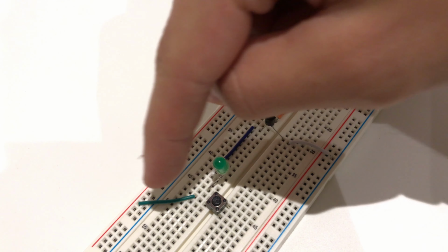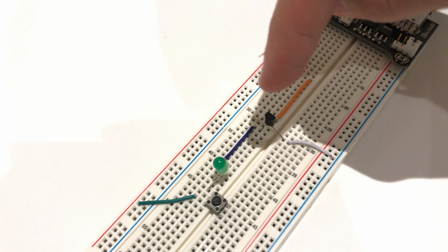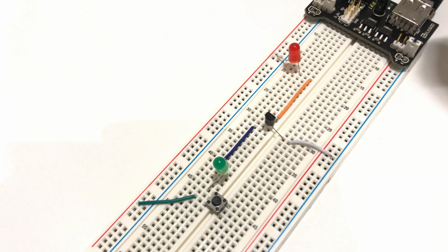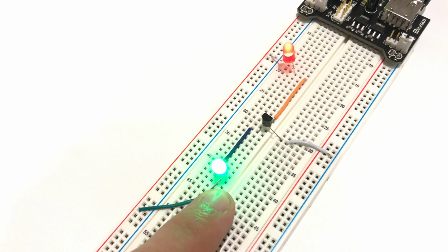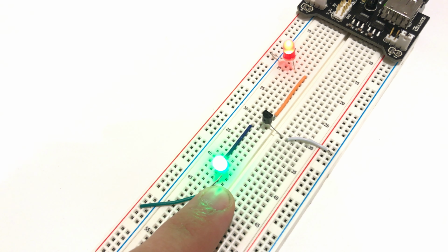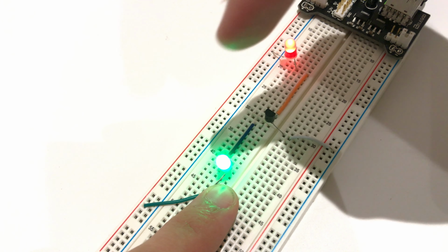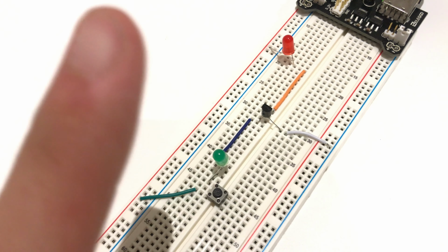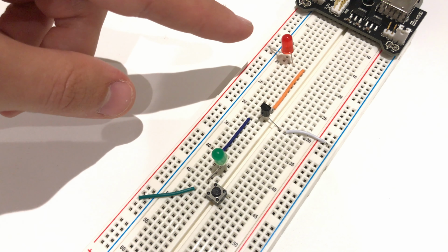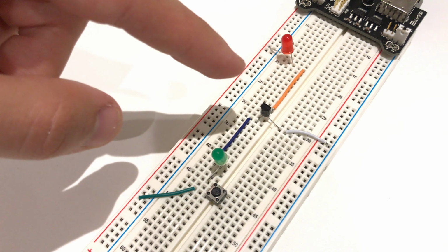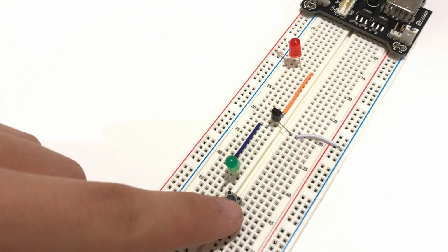So when this button is pressed, power can run through the button, through the LED, into the base, out of the emitter to ground. Allowing current to pass through the base, as shown by the green light, we can see that current is also able to pass through the collector to the emitter, as shown by the red LED. And when no current passes into the base wire of the transistor, we can see that no current can pass through the transistor from the collector to the emitter either, hence the red light has gone off.